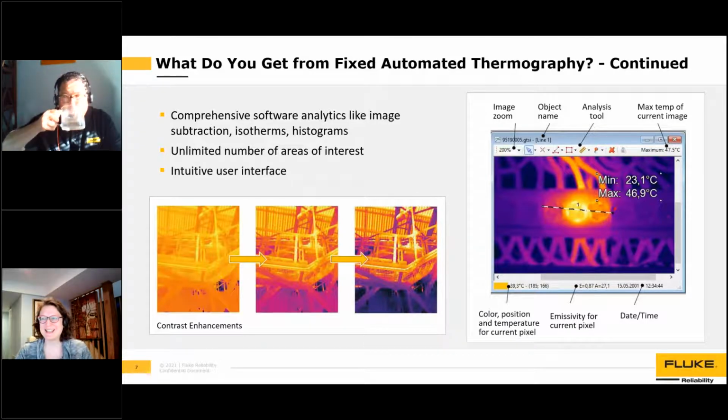So the first question is, do people typically establish baselines? Yes. It is always good to have a baseline understanding of your system. I always recommend having a baseline so that you understand how things change over time. We all know that temperature of a system, depending on what kind of environment you're in, can definitely change from season to season. So knowing what you're up against ahead of time gives you a good feel for what parameters you should establish for alarm conditions.